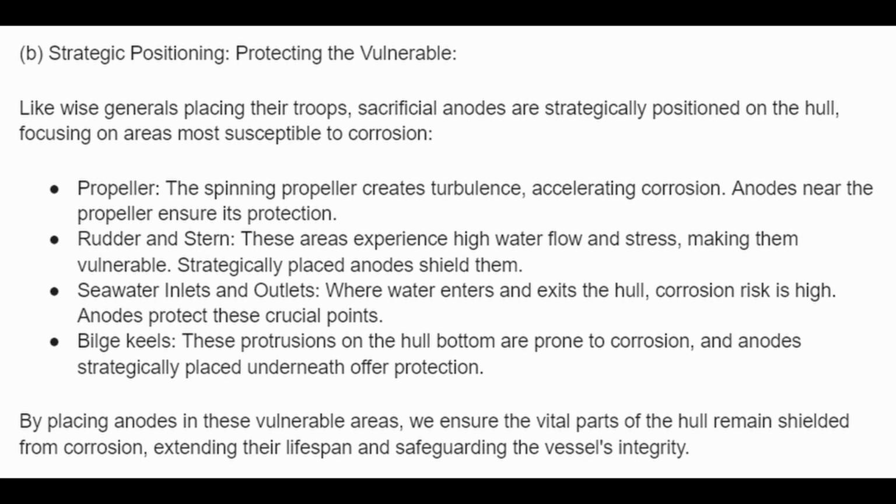Rudder and stem. These areas experience high water flow and stress, making them vulnerable. Strategically placed anodes shield them. Seawater inlets and outlets. Where water enters and exits the hull, corrosion risk is high. Anodes protect these crucial points.